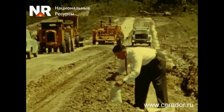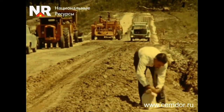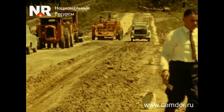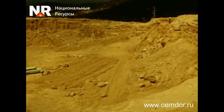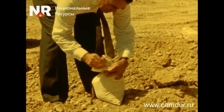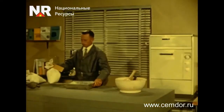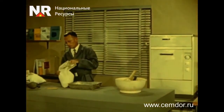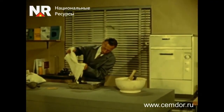To determine the suitability of the soil for constructing the structural layer, samples are taken from the road's right-of-way at regular intervals. When using imported soil or a special soil quarry, it is also necessary to systematically analyze the samples. In the laboratory, the samples undergo several tests to select the soil concrete mix, determining the optimal amount of cement and water to obtain soil concrete with the required set of physical and mechanical properties.